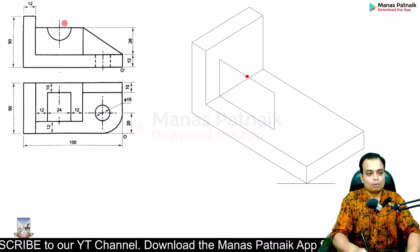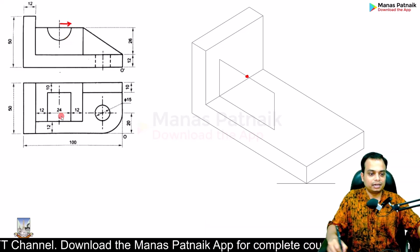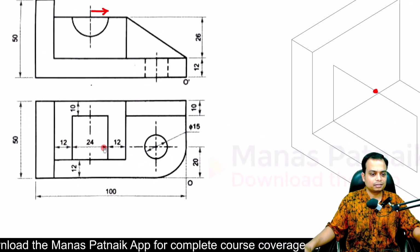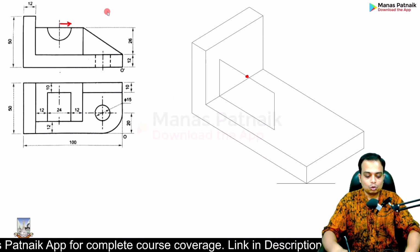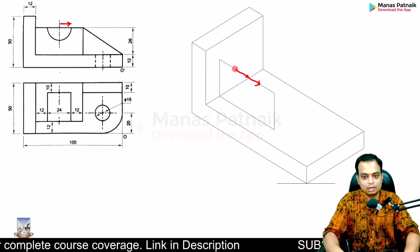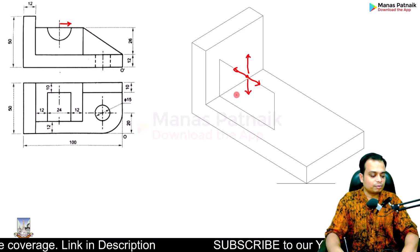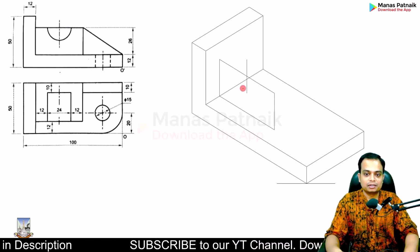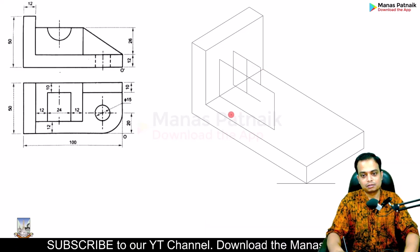Once again, what is the radius of this semicircular profile? Sir, the diameter happens to be 24. So this is the diameter 24. Half of diameter is radius, that is going to be 12. So 12 to the right, 12 to the left, 12 above, 12 below, and from here we can construct the isometric view of the semicircle this way. Okay, please close it, this way, this way, this way.